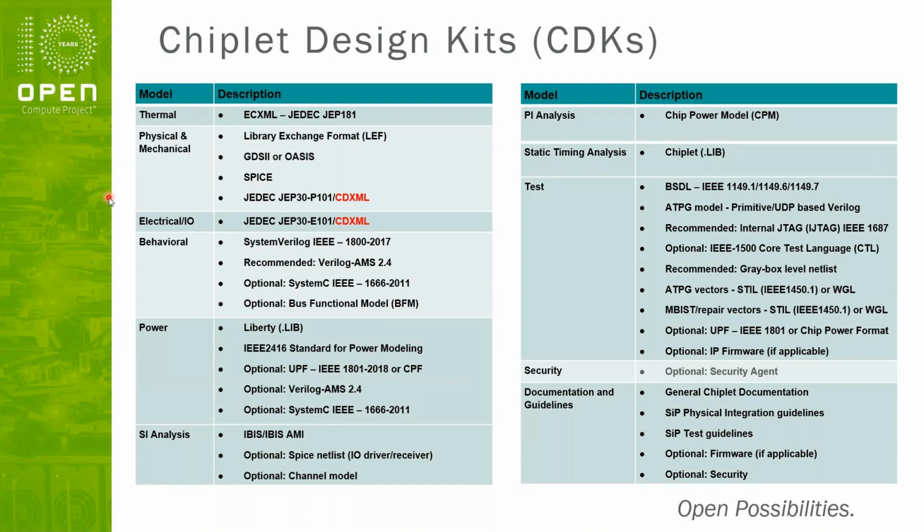The bump, is it a copper pillar? The mechanical tolerances, and there really are no standards out there. So we took an initiative to create a format to capture the mechanical type information, the size of the die, the package and stuff. A lot of this existed in the JEP30 standard for board level components.